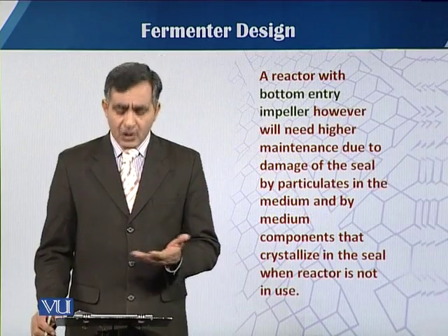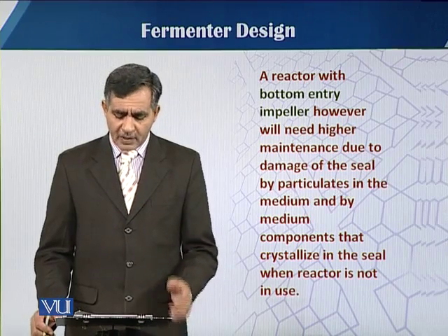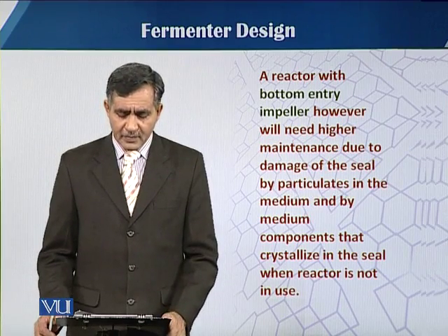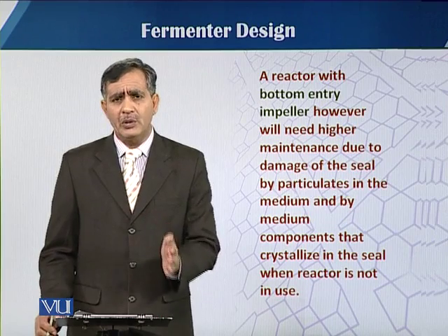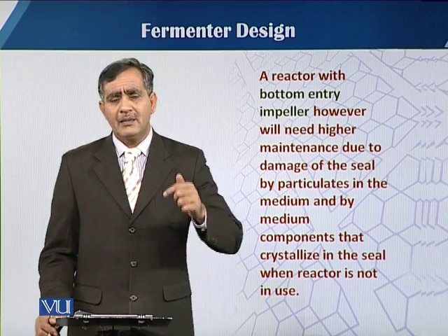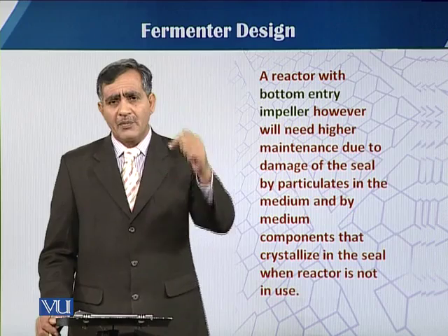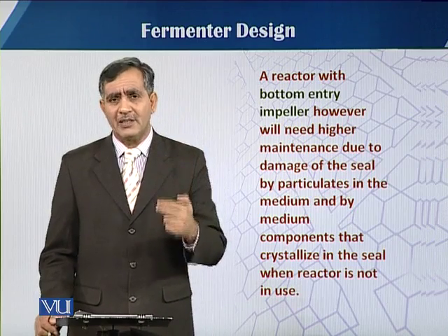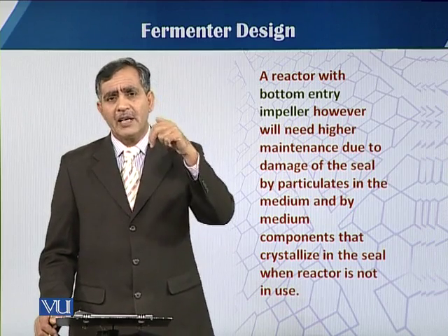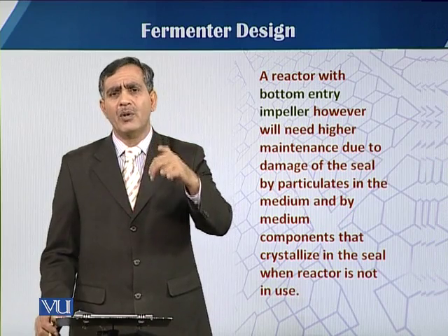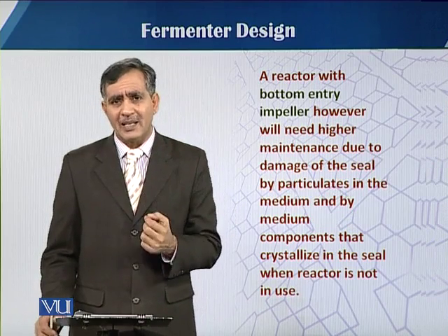A reactor with bottom entry impellers, however, will need higher maintenance, because either way, whether the shaft enters from the bottom or from the top, there is some limitation. When the shaft enters from the top, it is more expensive because the seal is very critical.